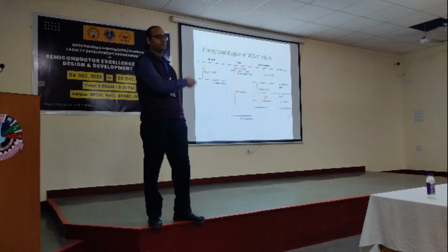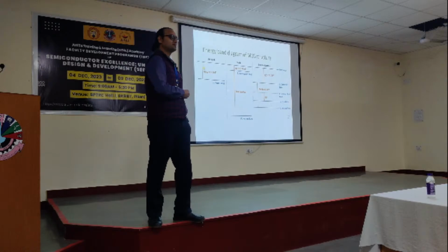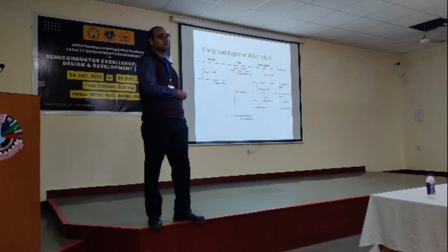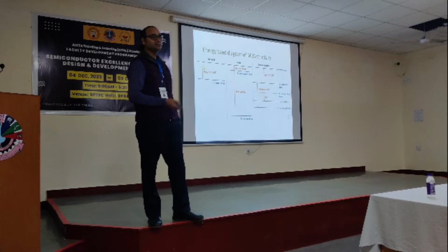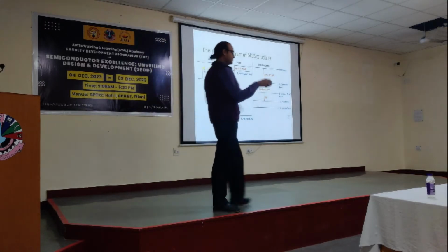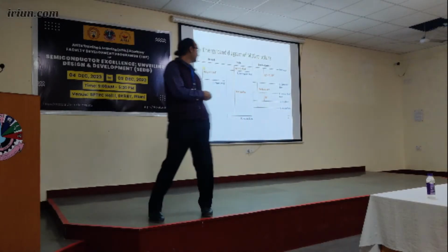Okay, so both according to his question, both the possibilities are there. Electrons might get shifted either this way or that way. If electrons are getting shifted towards the semiconductor, there will be depletion. If the reverse happens, there will be accumulation. First we have to make the bands flat, right? We call that the flat band voltage.